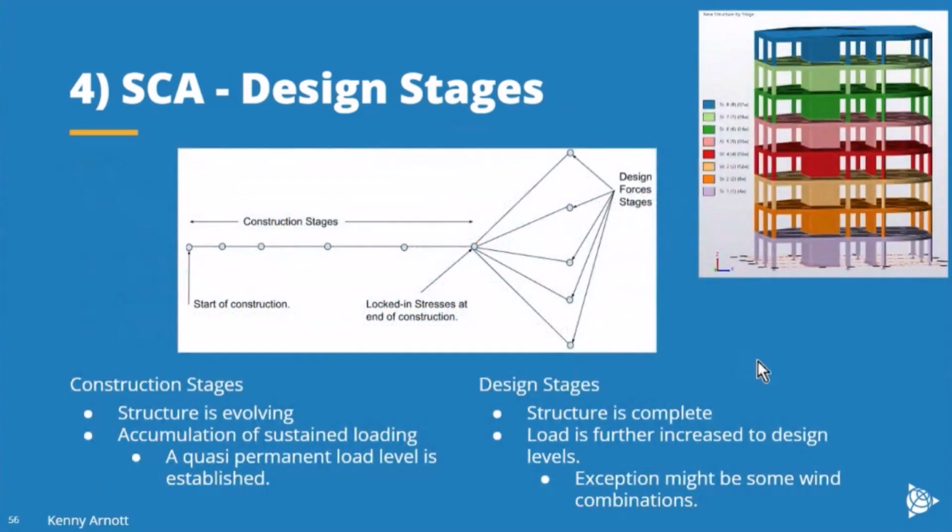So I'm repeating to some degree what I talked about in webinar 3. Our timeline here, where we've got construction stages where the structure is evolving and there is construction stage loading accumulating. So at the end of construction, we've got a completed building with some sort of quasi-permanent load level established. And then from there, we go on to consider design stages, where we can look at all the load combinations that would normally be considered, each assigned to one of these 5 design stages.